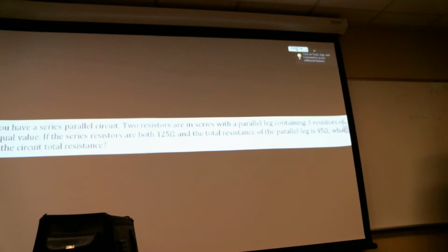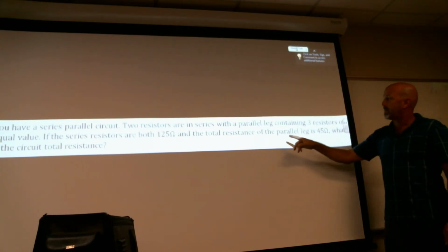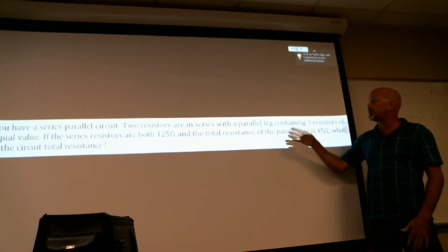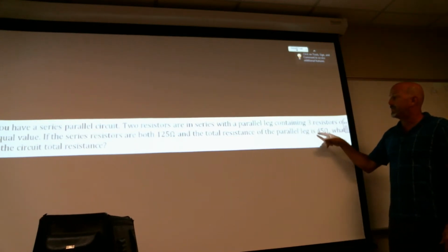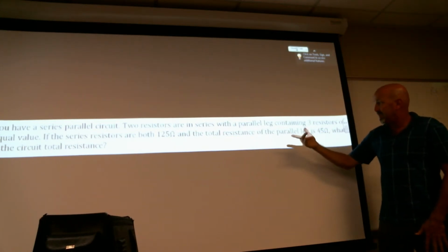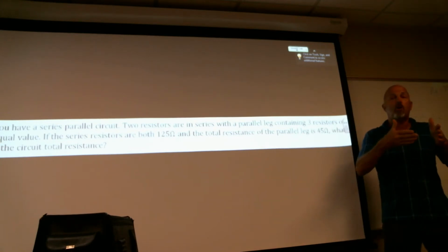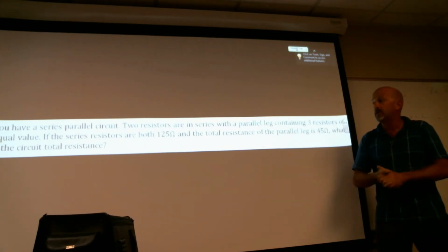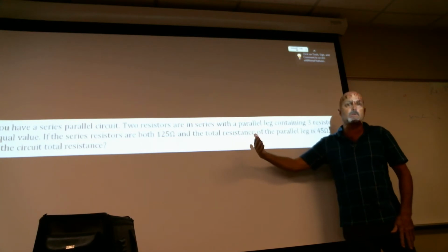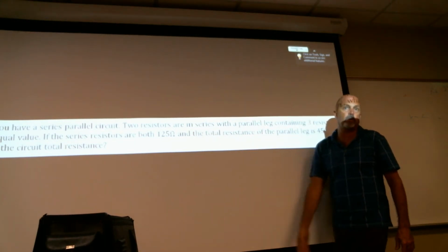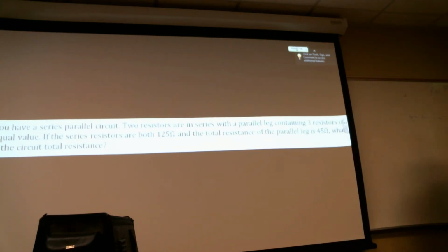So they threw you off for the three resistors. Yes, it throws you off. They could say the 3 resistors are all of them. They could give you the values, but they've basically saved you the trouble by just doing the parallel resistance for you. So it's a series, essentially, just add them all.